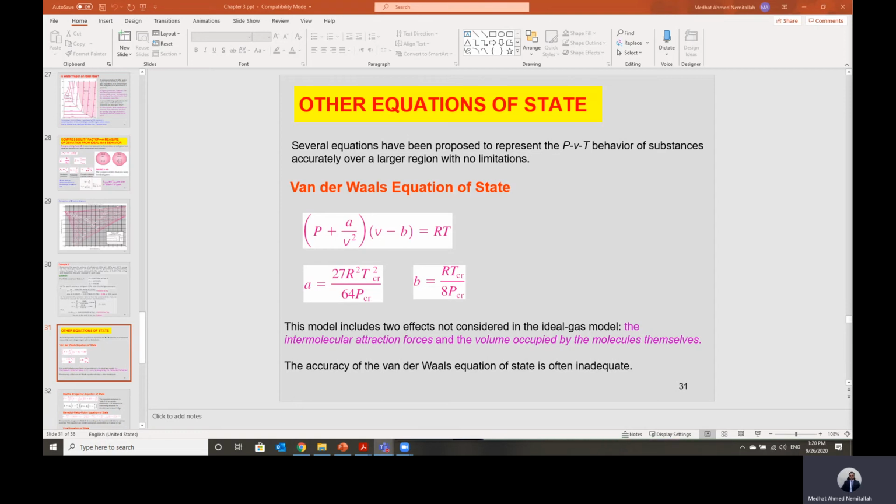When we have any two of them, like reduced pressure and reduced temperature, we can use chart A15 to calculate the compressibility factor Z. Then we can apply the modified equation of state Pv = ZRT to calculate the actual volume of the gas if pressure and temperature are given.